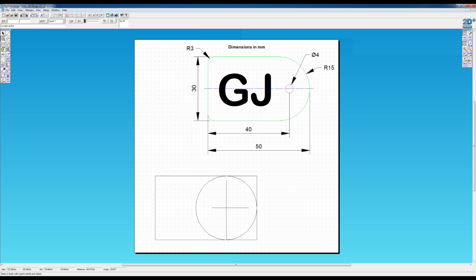It's a good habit to turn them off straight away. So I'll go back in, turn it off, uncheck, and we'll go back onto step lock. We're still in a circle tool, which is allowing us to draw another circle. To get out of it, the easiest way is to simply right click, and then we'll default back to the select tool.